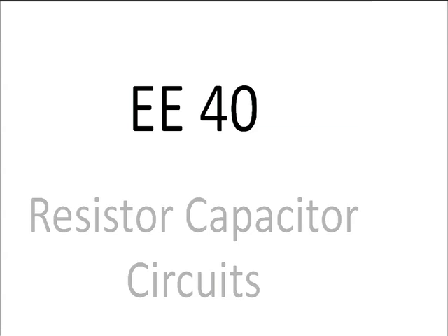Well, it doesn't really, but it can see capacitance because our finger is mainly water. The dielectric constant is much higher than that of the air, so if we put the finger on the touch screen, the capacitance changes of wires that are invisible, made of ITO, and then we can build a circuit that, for example, can use a switched capacitor approach to actually measure the capacitance and detect whether a finger is there or not.